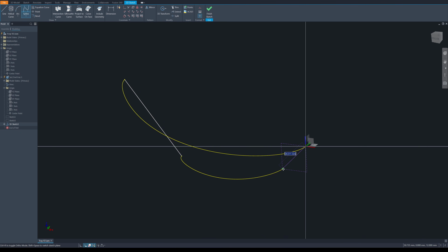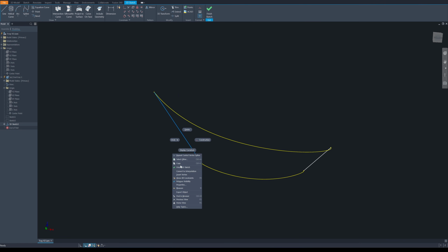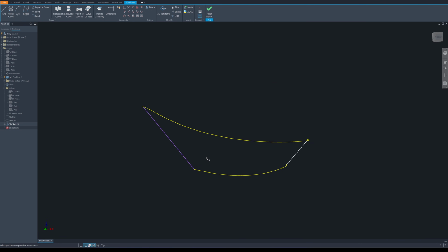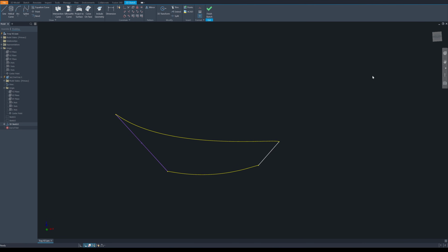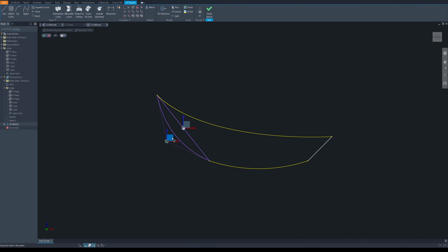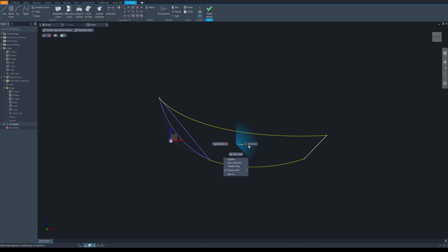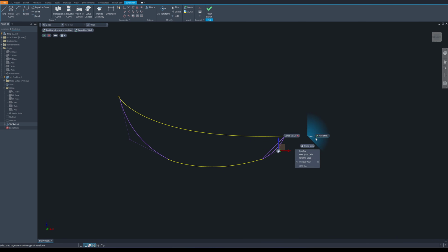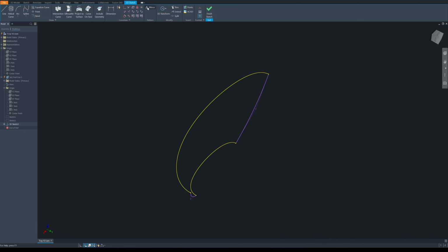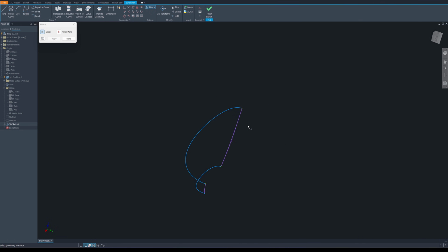In 3D sketch, I create two of the splines, add one vertex for each spline. Then I move the vertex to adjust the curve. Next, I'm going to mirror the curve using the XZ plane.